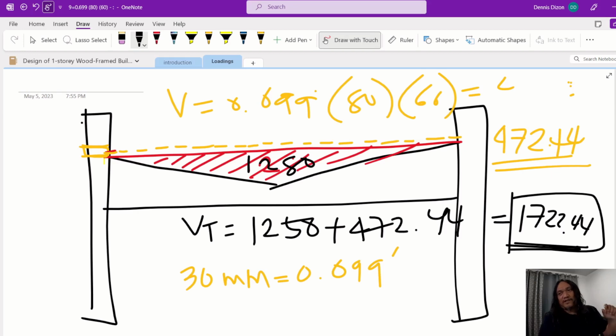So, therefore, at maximum precipitation, like 1 in 50 year for one day occurrence, it will not fully occupy, well, it will occupy the roof, but not the total maximum height allowed, which is 10 inches plus 30 millimeter, right?